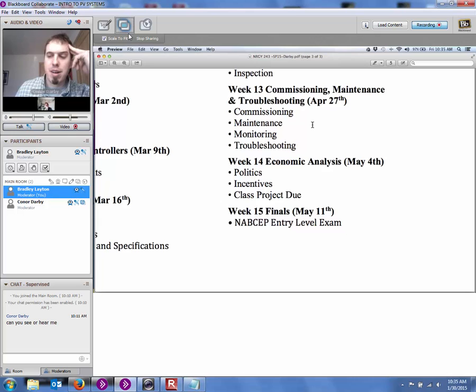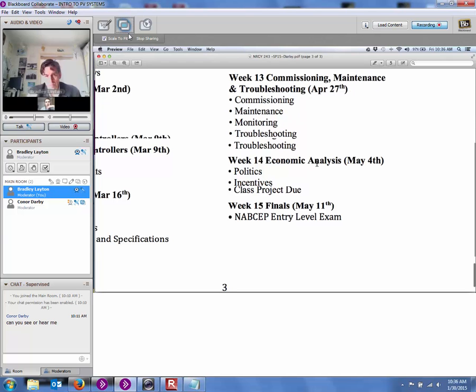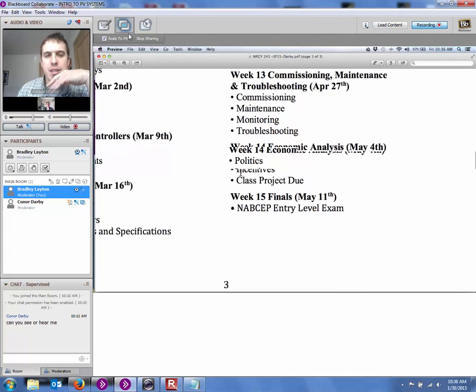Okay, now the whole thing is installed, well, let's turn it on and see what it does and play with it and test it and make sure that everything is working according to plan, and also recording data, so taking initial data sets based on things like solar irradiance and temperature and time of year, and calculating off those coefficients to make sure that your system's producing what it should be at any one time based on measurements that you're taking of solar resource and temperature, etc. And then lastly, economic analysis.